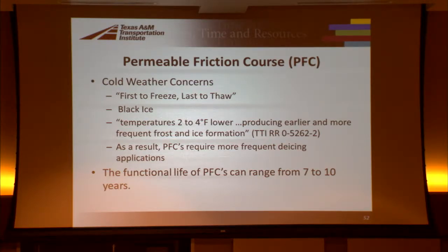Mark McKendry, Stephenville area engineer, told me a story. He was driving from Comanche County into Dublin, and he went from a microsurfacing to a PFC and spun out of control when he hit it. We started hearing more and more of these stories from the maintenance forces, and that was one reason why we got away from it. Even though we thought we got a more durable mix, even on the high volume roadways, we still had this black ice concern.